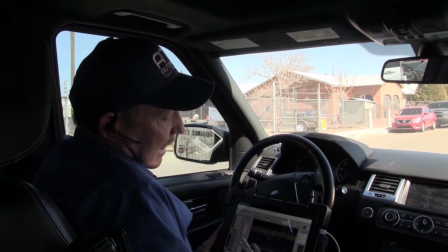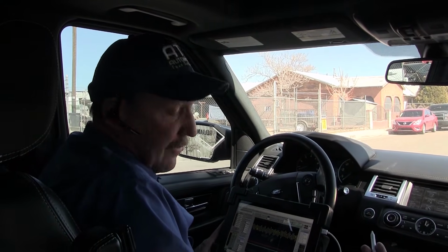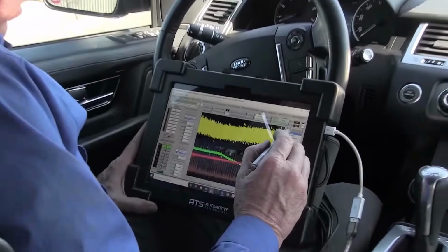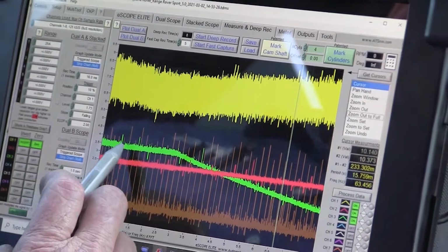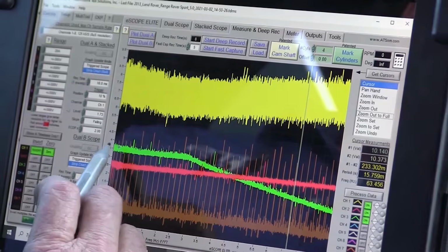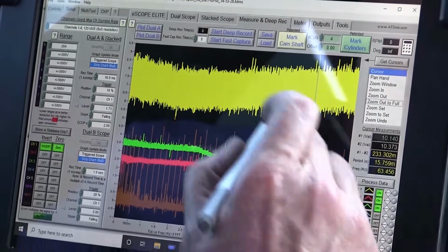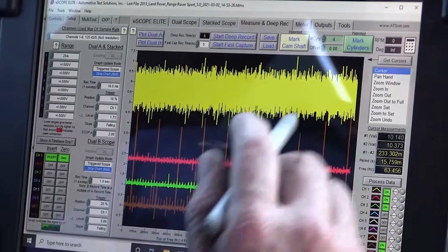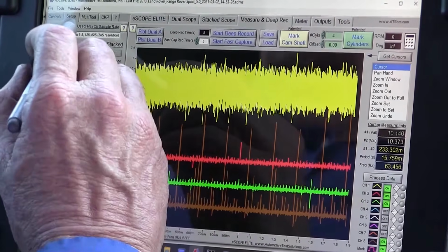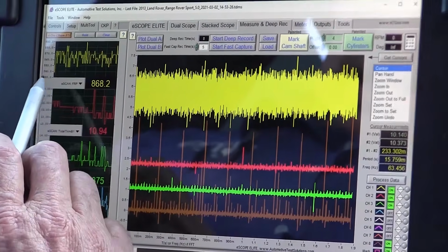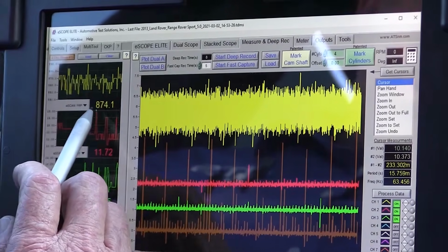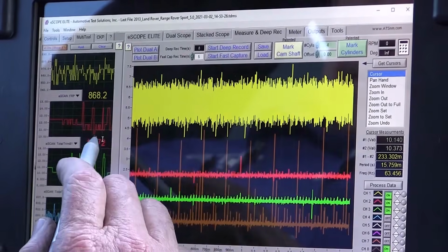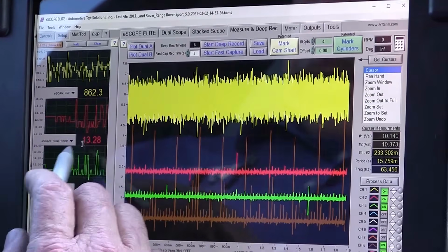I would think at idle this would be about a 3,500 RPM pump, so that would appear to be correct. We can see where my high pressure was up when we first started it. We're pushing more pressure, and then it comes down to a control level. Now that it's been sitting here idling, let's check it again. The scan tool is reading the fuel pressure, so I know I've got my rail pressure at this time, and my trims are doing pretty good right now too.